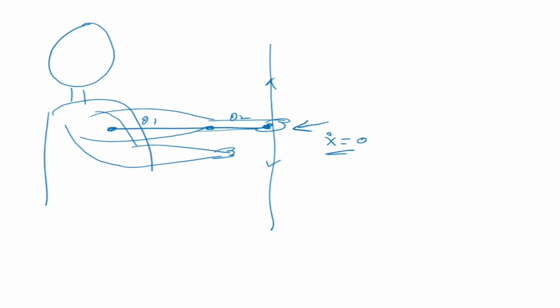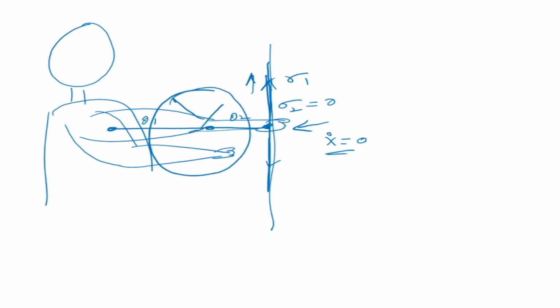And the direction of the velocity ellipsoid says that sigma 2 is 0 here now. Only sigma 1 is there. It means sigma 1 is in this direction, so you can move up and down, but you can't go this way. Whereas in the center of the workspace, you can move equally in all directions. Please bring your hand to the center of the workspace where your theta 2 is 90 degrees.